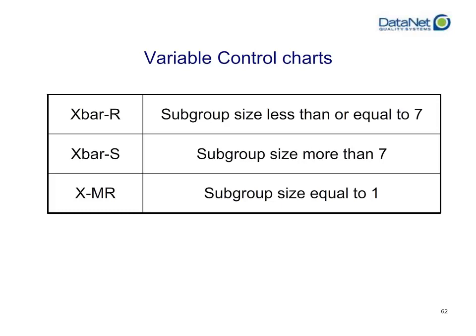But within WinSPC, at least, there is no magic number that we're going to flip between going from a subgroup size, between using by default an Xbar-R chart versus an Xbar and S chart. It's really up to your personal preference what you want to see and what your quality engineers are used to seeing as far as what is the best chart to use in your process.